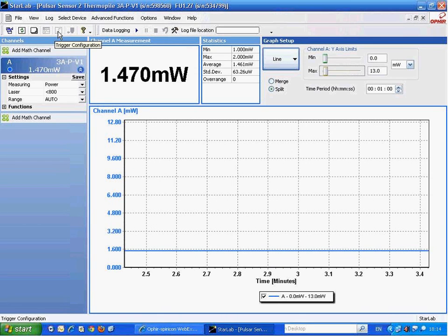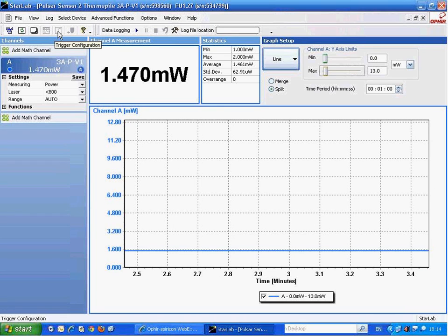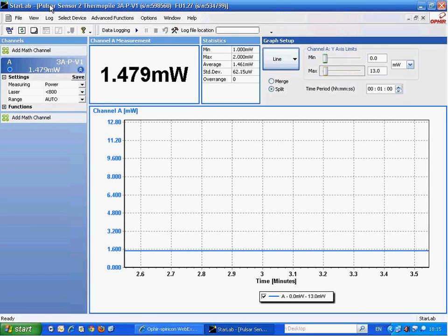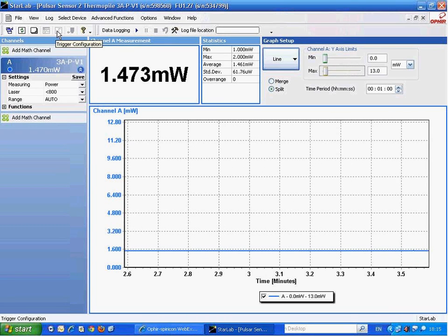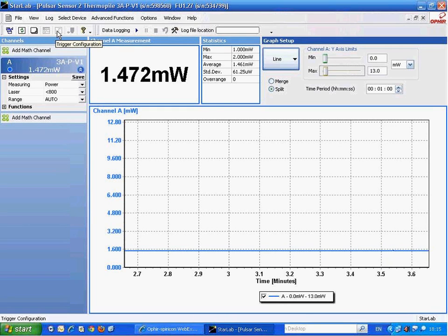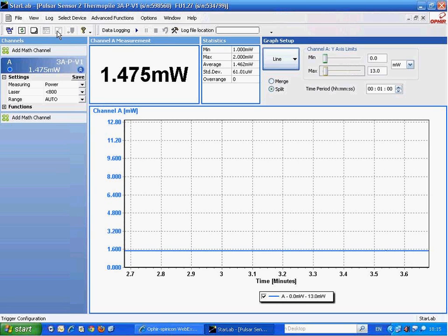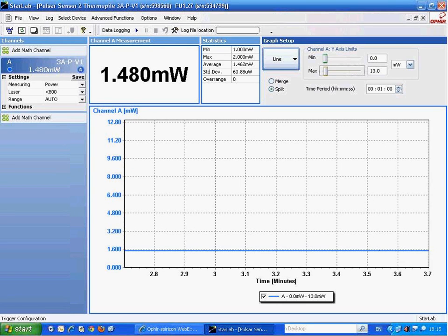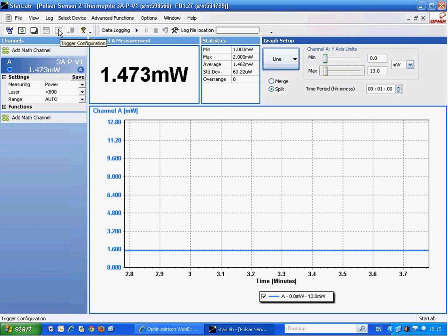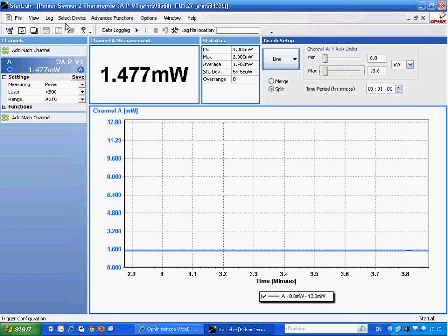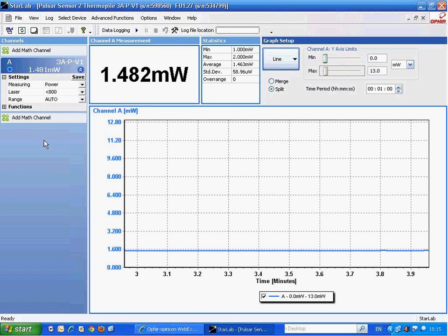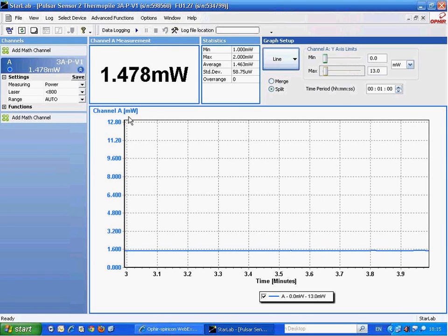This is trigger configuration. If we're using a pyroelectric sensor and specifically the Pulsar instrument, which actually we were using together with the pyro sensor, the Pulsar makes possible the function of detecting missing pulses. And for that purpose, one needs to configure the trigger setup to look for rising edge, falling edge, etc. Because right now we're actually connected to a thermal sensor that is inactive, as you can see. Others as they become relevant.